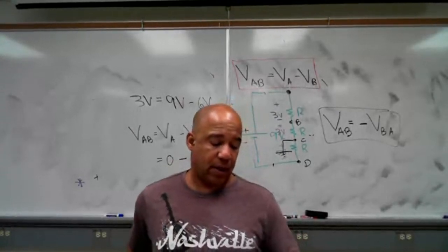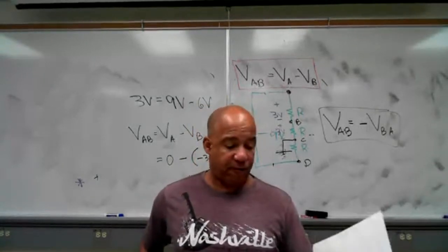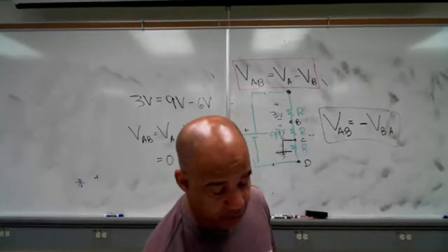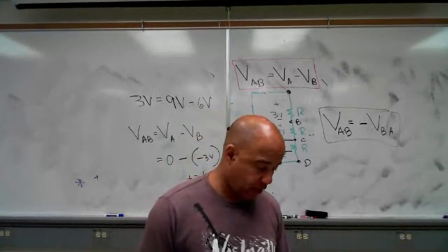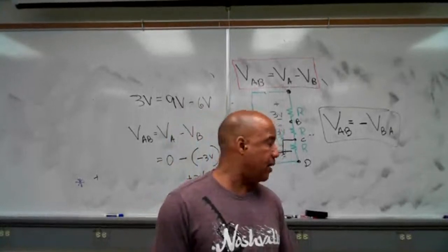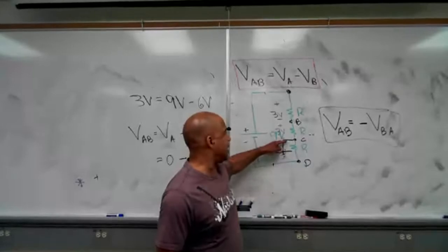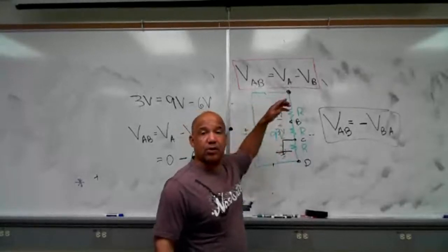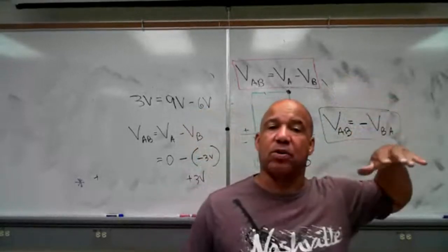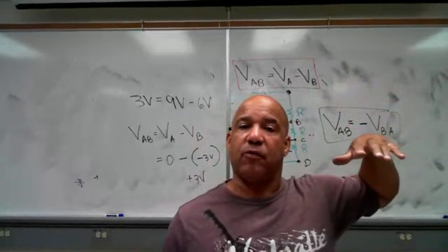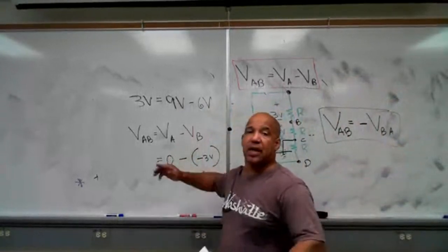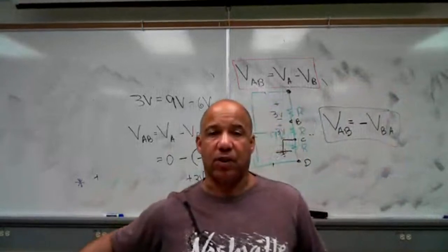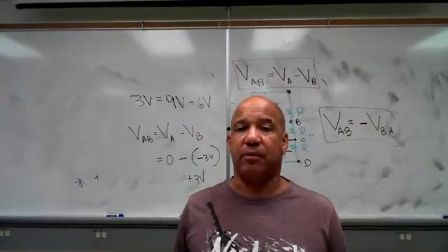And then you'll do the same thing in table 4.5, and I don't know if there's another one. Yeah, and then in table 4.6. So you'll move the reference from D to C to B up to A. And you'll see that all your measurements are different for single subscript notation, but when you do this difference calculation, it should prove to you that the voltage drop across each resistor remains the same.